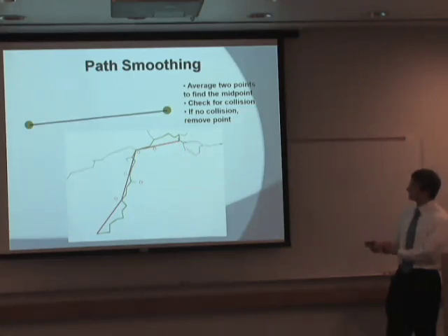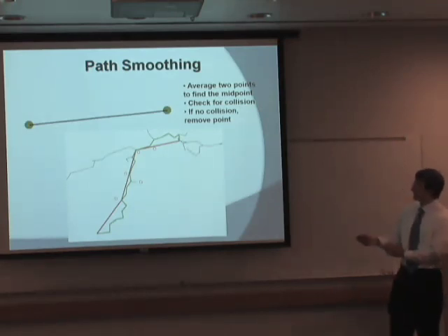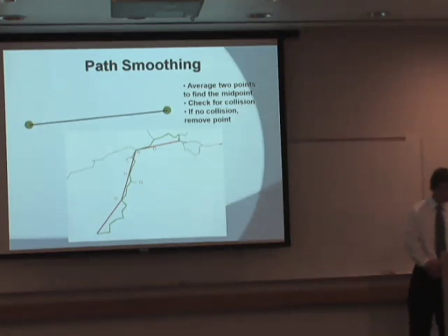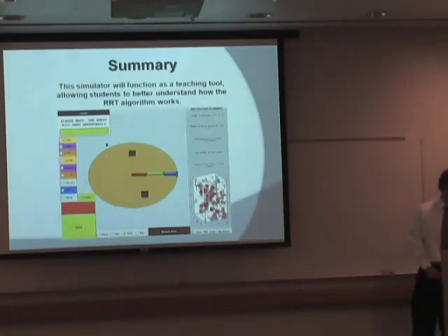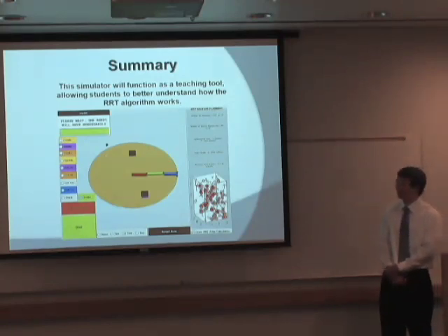It's only 1, 2, 3, 4 points in that path, as opposed to maybe 20, 25 for the green one. The red line did not go absolutely straight from the start to the end, because there were certain obstacle points that would cause collisions. So the path smoothing is very important in optimizing the arm's path.